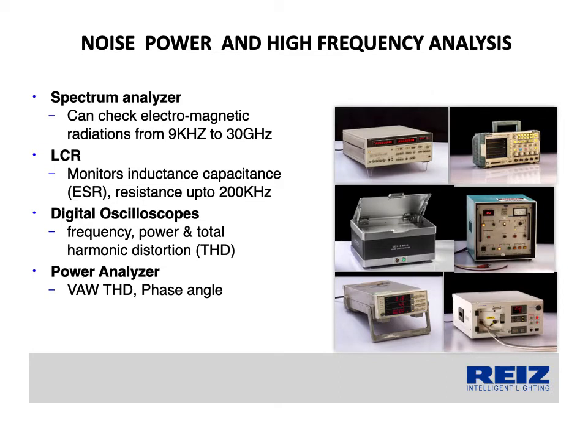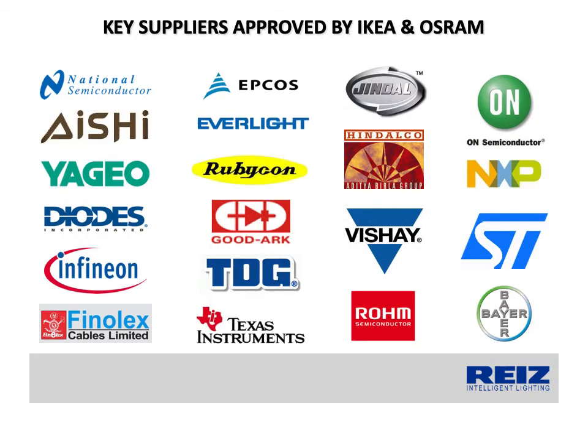As LED drivers work at high frequencies, factories with sensitive equipment must check that all LED lighting conforms to bare minimum noise specifications. An important prerequisite for a 5-year warranty is that all components that go into an LED luminaire must be sourced from reliable, internationally approved suppliers.